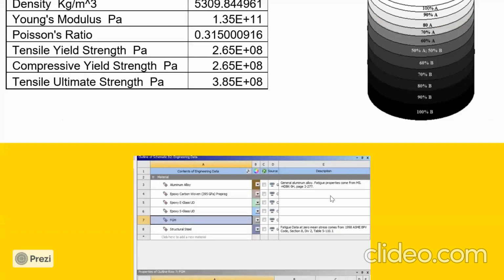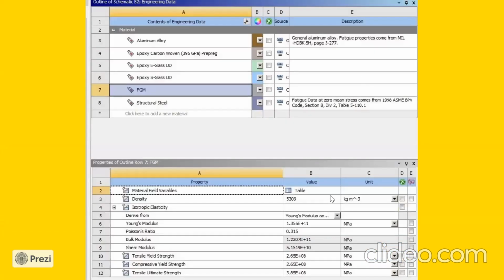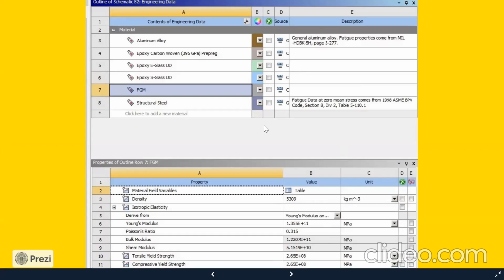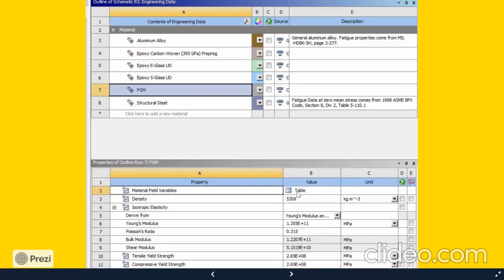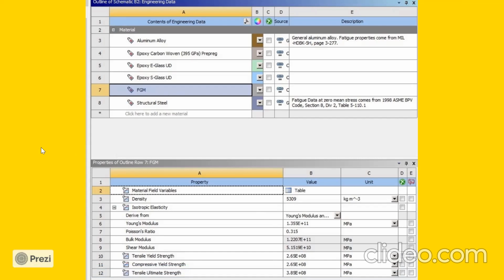use. In ANSYS there is no FGM material. That means you will make it. So we make a calculation Excel sheet between the 2 types of material. Then we take the average. After that, we add a new material in ANSYS, and we name it FGM material. Then we put in the values of the mechanical properties. After that, we use it as a material.